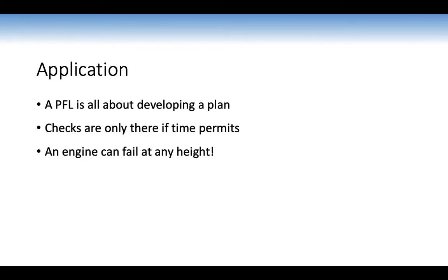Application: PFL is all about developing a plan, but don't be afraid to change it depending on the situation. Checks are only there if time permits. You'd rather make the field and have done none of the checks than do all the checks but not make the field. An engine can fail at any height, so it's really important to always be looking for plan B and always aim to fly as high as possible. If the engine does fail, you've got a lot of time.